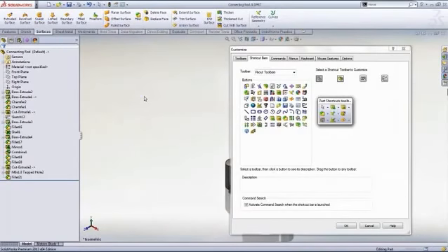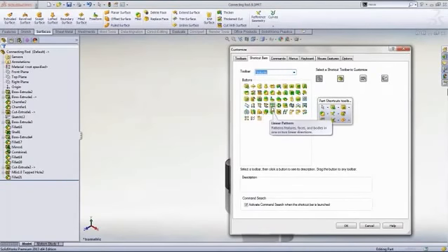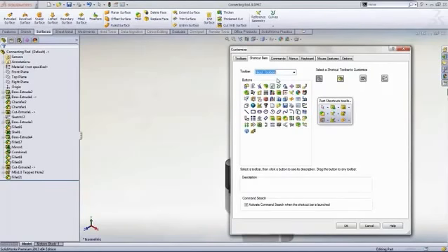Now, I'm using SOLIDWORKS 2013 here, and this is a little easier in this version, but previous releases work fairly similar. Here, in this drop-down, you'll see that I have access to all the tools in the software. For instance, maybe I want to add some of these pattern tools from the features list. A better way to manage those might be using a flyout, and if we scroll back up to the top, the first item in the list is flyout toolbars. These basically represent all those standard toolbars I just mentioned, and there happens to be one for patterns.